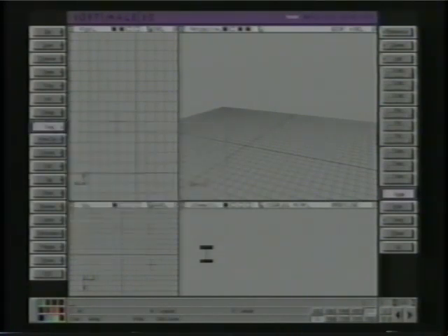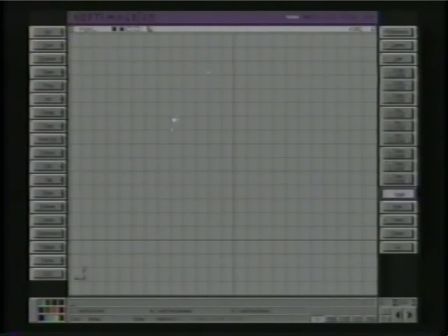Now about cardinal curves. Draw a cardinal curve. You'll notice that the curve will always pass directly through the points, which sounds like a nice thing, but it can create some oddities. For instance, if I move this too close to the other one, it'll actually fold over itself. Obviously not often a very desirable thing. It also has a long range of effects. So for instance, if I move this around, you see that it affects the curve all the way up till this point here. Move that, it affects all the way up there.